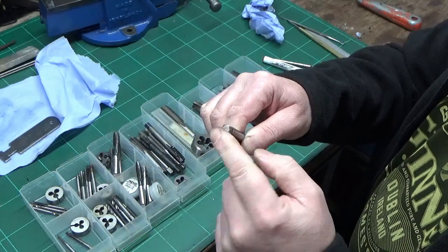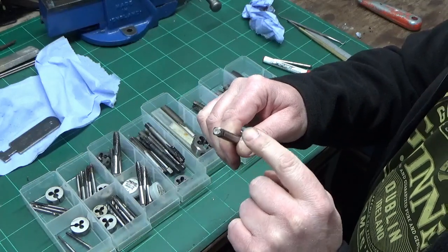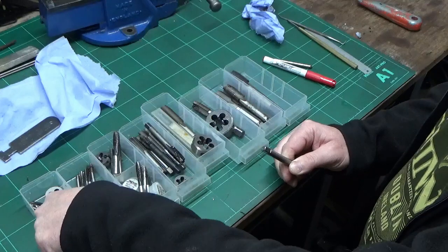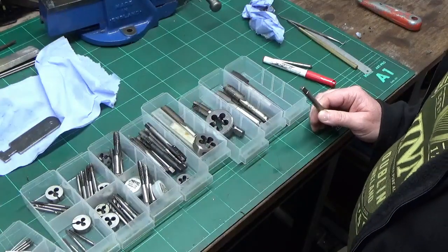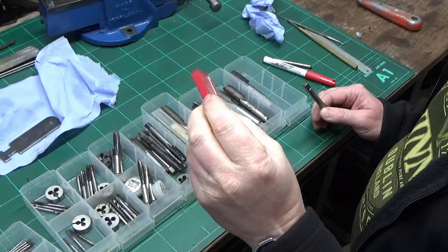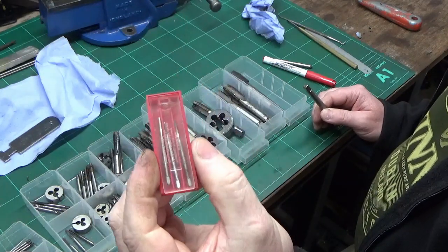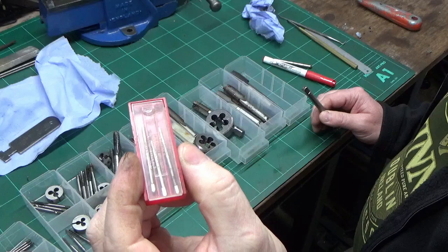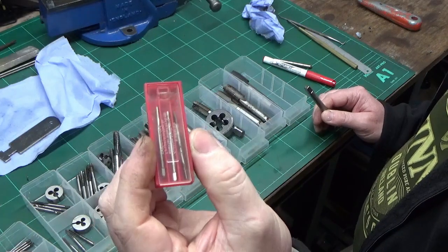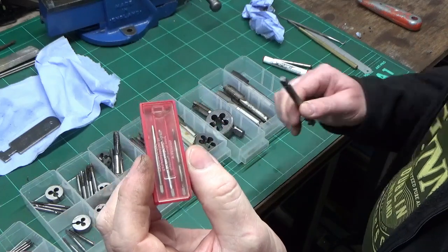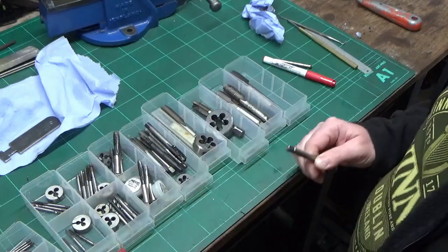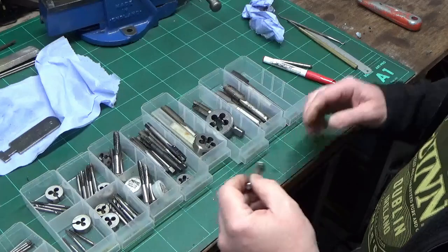So the range the cup needs to cover is this being the biggest square, and probably actually I've got a smaller set of taps here going right down to 1mm being the smallest square. So I need a cone shaped cup that's going to cope with the difference in square size between these taps and this tap. So that's my sort of design constraints.